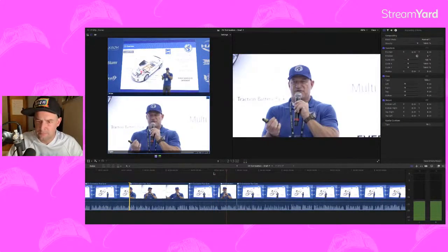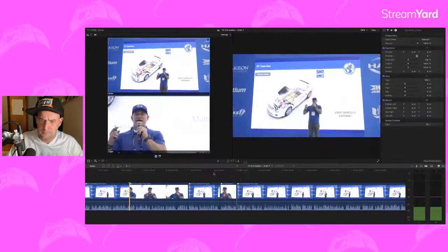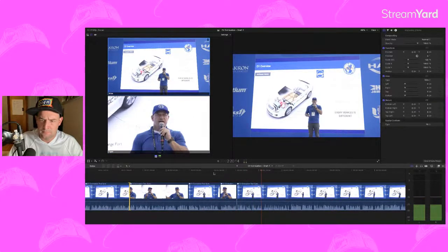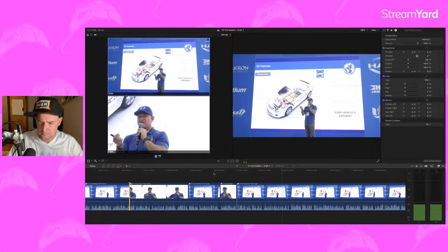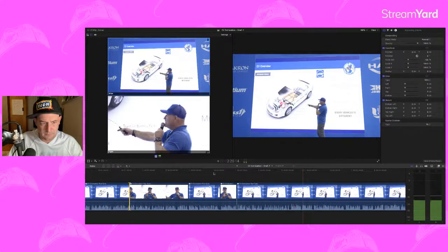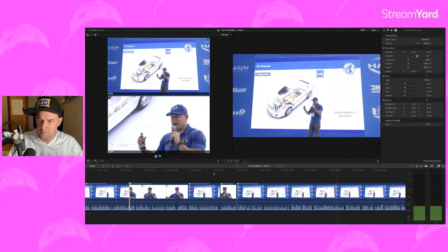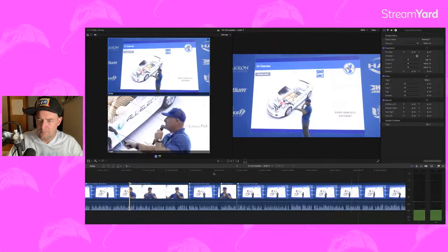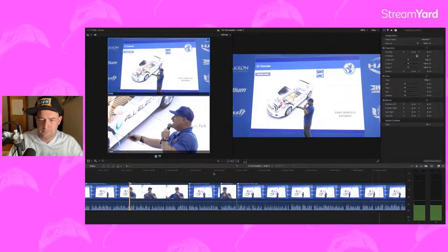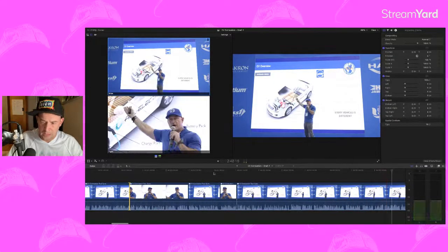This usually resonates with firefighters, and this is to communicate: think of every electric vehicle as a circuit, or a system. Every single piece of equipment that is part of that circuit is a point of concern. As we look at this, we evaluate what's on here. We've got our high voltage traction battery pack. We're going to have a plug coming in. These can be a variety of levels of plug capability and charging capabilities. We're going to have high voltage cabling coming off the traction battery pack. We're always going to have an electric traction motor. You may have a singular motor in the front.